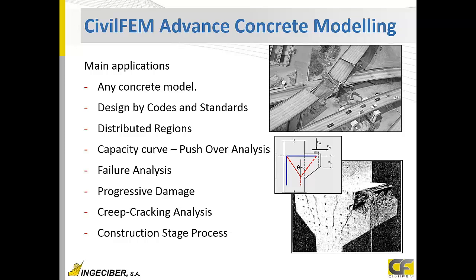We have a long list of codes to design for bending plus axial, shear, in-plane shear, cracking. And in some zones where those codes cannot be used, like disturbed regions, where stress distribution is not linear, we can use this nonlinear modeling to get reinforcement and design correctly.